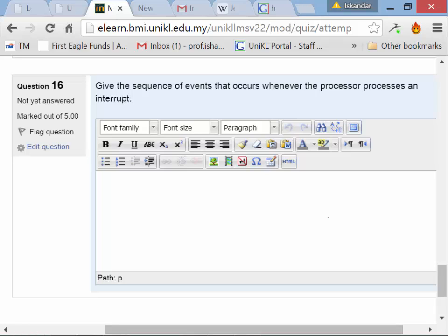When it comes to the statement return from interrupt, it will then pop off the program counter along with the register set and return back to where it was. So we're looking for something along that set of events. Your best bet is just type this as a list, memorize the list of what happens in the course of that. And again, it's in both textbooks. And actually, I think I had a slide with that on there too.